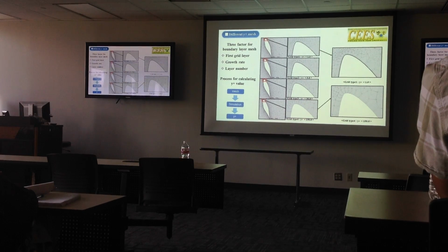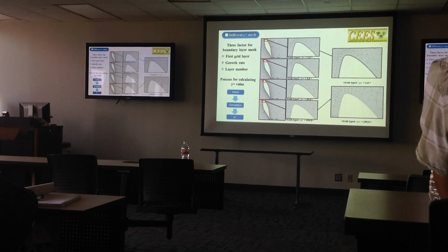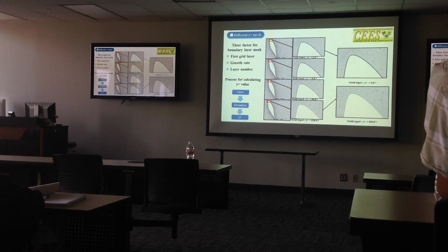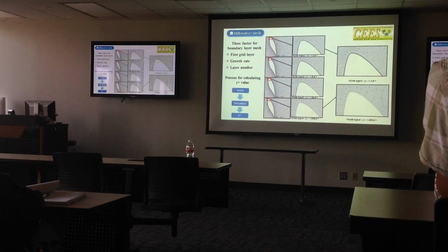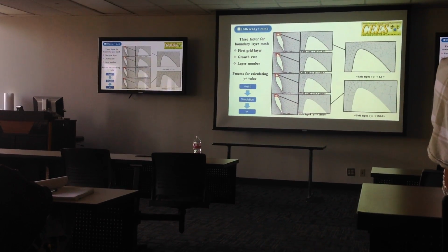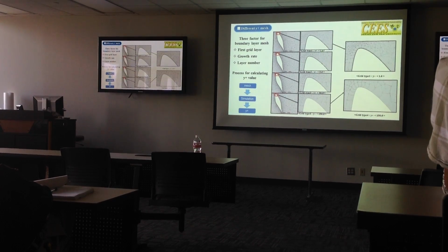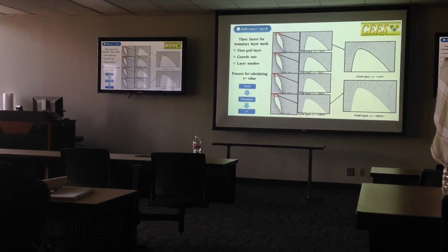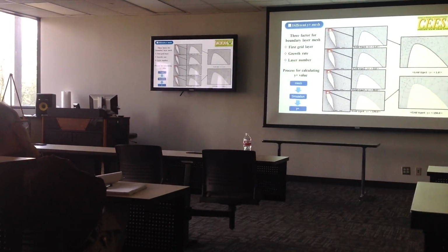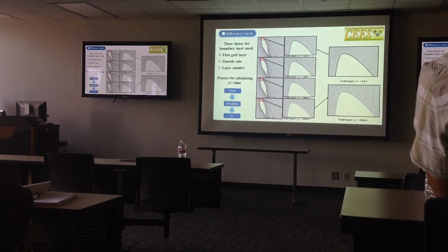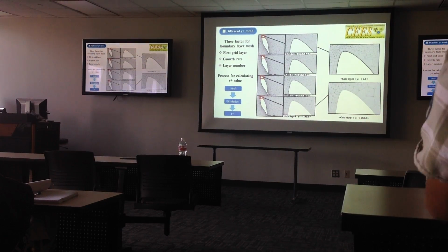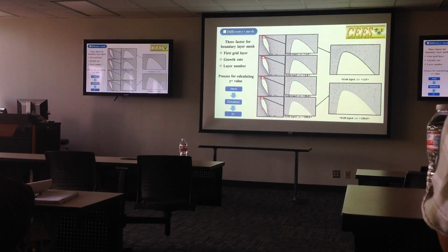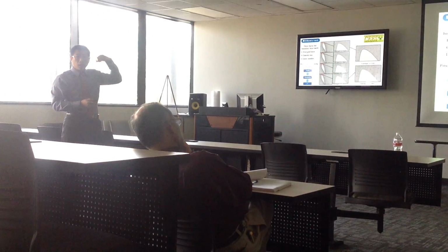After the different meshes are defined, we run the simulation. After convergence, we can get the result, and we can calculate our Y plus based on the equation I mentioned in the previous slide. At that time, we can confirm the Y plus value in this region. Then we connect the different results with different Y plus. In different cases, we compare our result with the experimental data. As I mentioned previously, this is the wind tunnel test data to check our simulation. That's the guideline of our simulation.